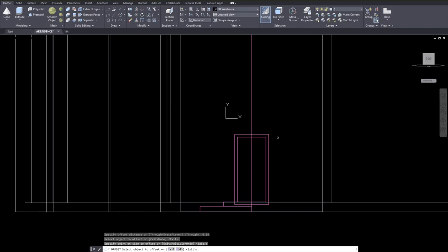All right. And this is going to be the door opening, but I expect to have 2 windows on both sides of the door. Okay. And also the bottom frame needs to be trimmed, so I'm going to use the trim command. In the trim, line cuts line, so we want these lines to be cut. Okay. I'm going to just simply explode this line so that I can trim it off partially.